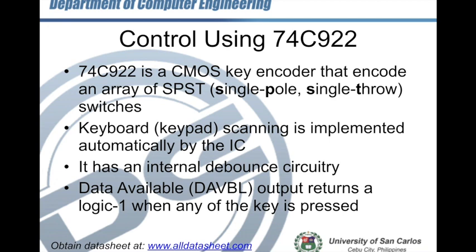The hassle of controlling the keypad is that you have to scan each column and read rows, plus you need a lookup table to identify which key is being pressed. That might take a toll on the logic of the program running on the microcontroller.